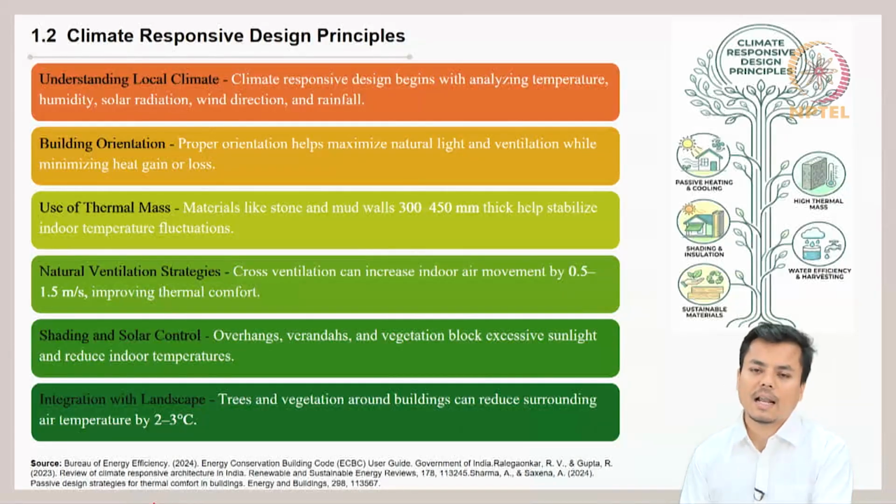Similarly, in cold and sunny climatic regions or in moderate ones, you have to go for deciduous trees, because in places where there are extreme winters, the plantation of deciduous trees helps in solar heat gain. These trees shed their leaves during winters and allow sunlight to enter the space. So, these are some strategies which you can use in your design to make it less dependent on active measures, and try to maximize the use of passive design strategies.